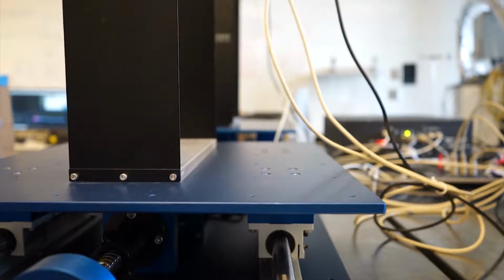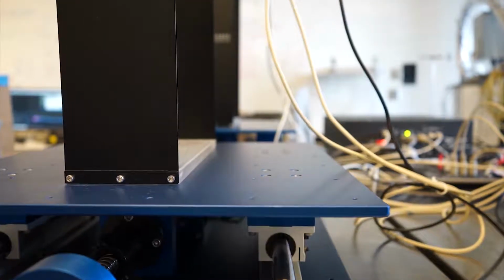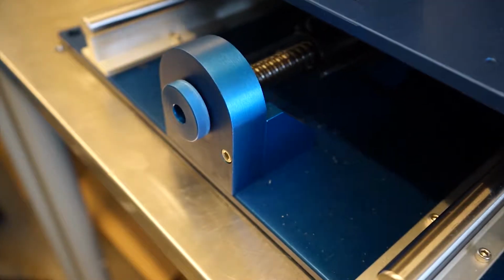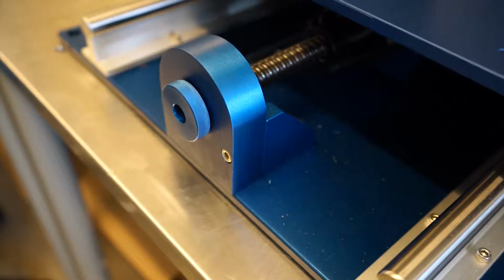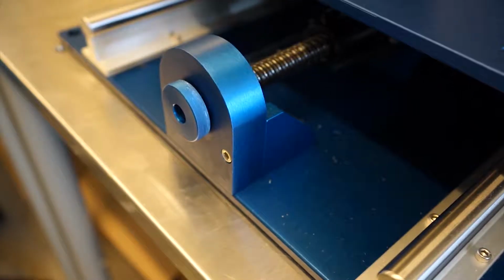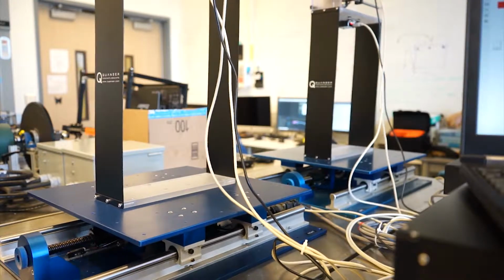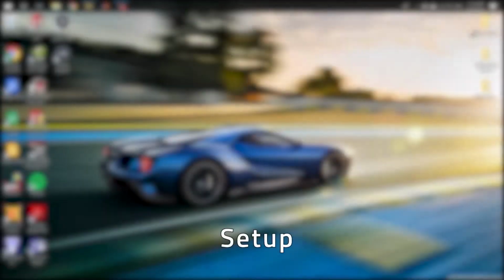The tabletop shake table setup can be used to demonstrate and investigate the effect of sinusoidal, vibrational, and seismic movements for different materials and scale models. When calibrated correctly, the shake table can simulate scale positional data of various acceleration curves in a very accurate manner.